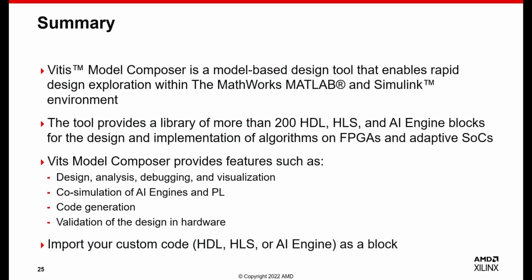Vitis Model Composer is a model-based design tool that enables rapid design exploration within the MathWorks MATLAB and Simulink environment. Vitis Model Composer provides a library of more than 200 RTL, HLS and AI engine blocks for the design and implementation on FPGAs and adaptive SoCs. Vitis Model Composer allows you to create, analyze, and debug your design. You can co-simulate AI engines and PL. It allows you to generate the code and validate it in the hardware. Also, Vitis Model Composer supports import of your custom code as a block.